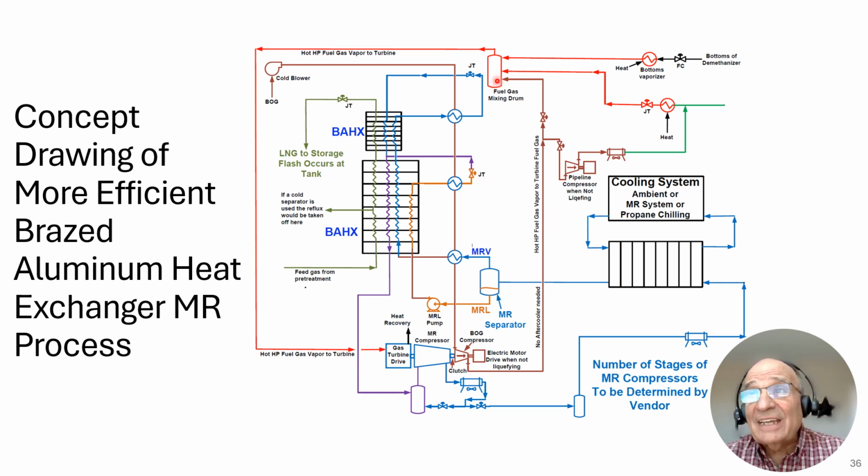And your turbine gas has to be around 220 degrees Fahrenheit in that order of magnitude, because you want to make sure that your turbine gas does not have any liquids in it, any drop of oil or condensate that may have knocked out.